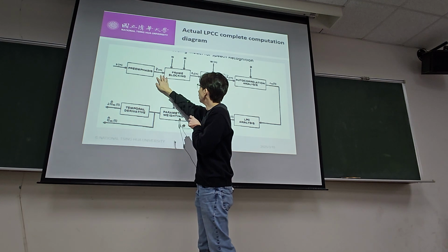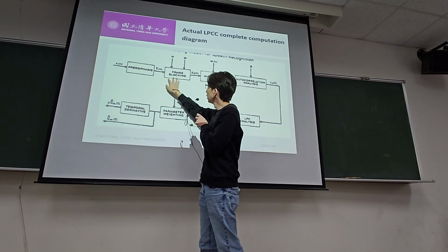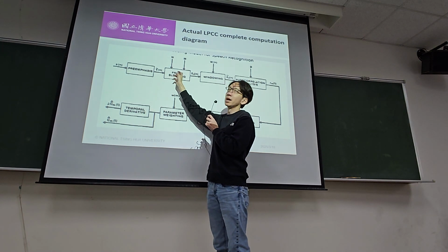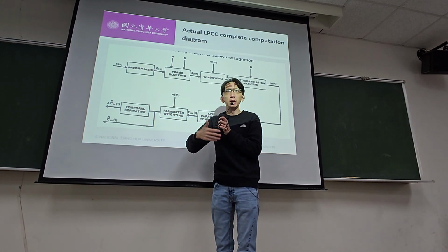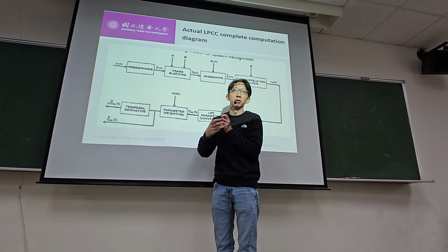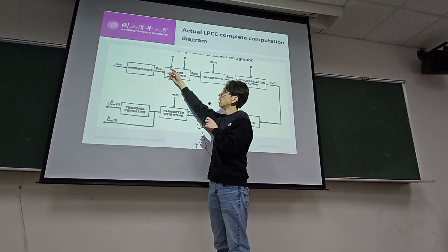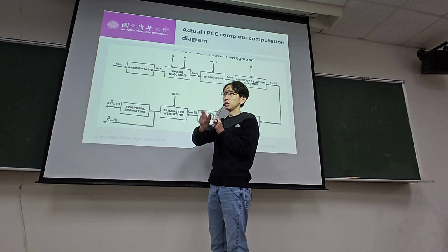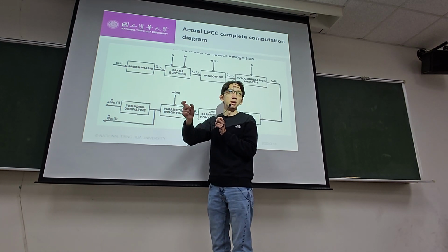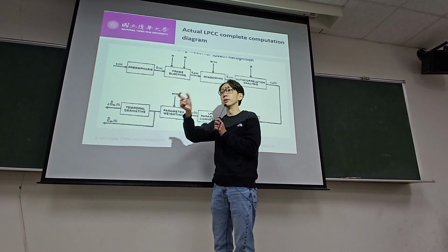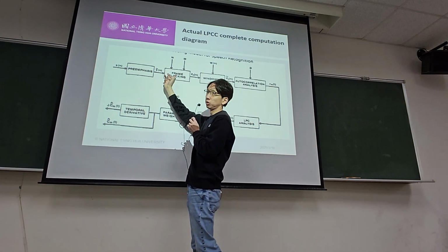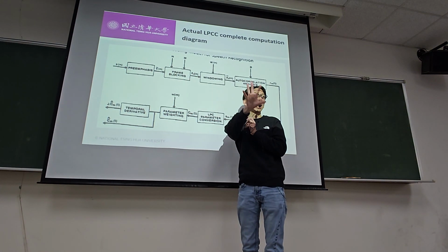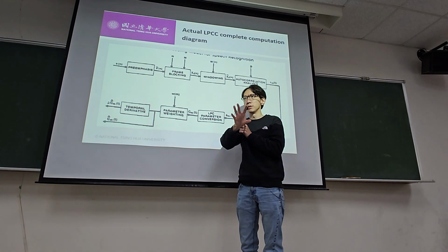Then we do frame blocking. We have two parameters, N and M, right? Frame blocking basically makes our signal short time. Choose the segment length that you want to analyze. Choose M, how much you want to slide, how much overlap you want between the frames. Now you have a blocked frame, a segment of the signal, which we call a short time signal.